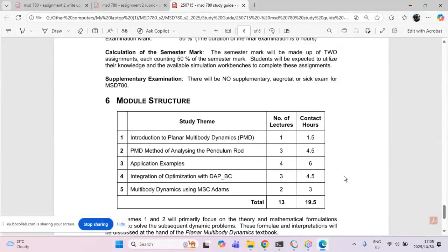We looked at one of the examples over there. Today we're going to look at a fairly simple example where we have a cart where we want to maximize some sort of a kinematic property related to the input torque or input loads. And that will also give us an idea of how we can go about defining the objective function and defining the design variables with any equality and inequality constraints.